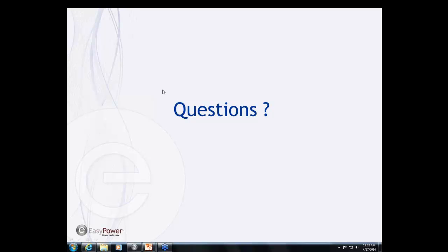And then there was another question regarding why the 1,000 second was used for the max time for this discussion. The 1,000 second max time was used to show these cases. Some people drop that down to 2 seconds or 5 seconds based on engineering judgment, or other methods. Basically, you're saying that if you drop it down, whoever's working there won't be in that area at that time. The 1,000 second was just used today so that the time would run completely and to be able to show what all these devices needed to do to trip.